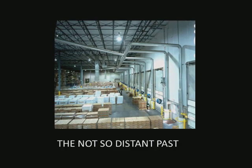Well, here's an example where they took the supply ductwork and ran it all the way down the side of the building in order to get the displacement ventilation effect. They're still bringing in that cool air closer to the ground. Well, in the modern construction industry, as it has been for many years, trades are always arguing and fighting over the very limited space in ceilings. And I think the last thing we want to do is have ductwork coming down not only along the ceiling, but inside all of the interior walls where electricians and plumbers and so forth may not be used to working around it.